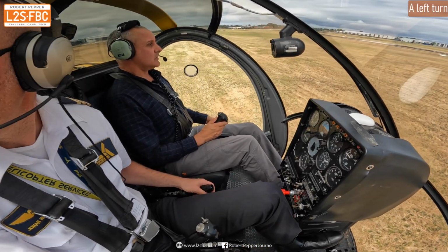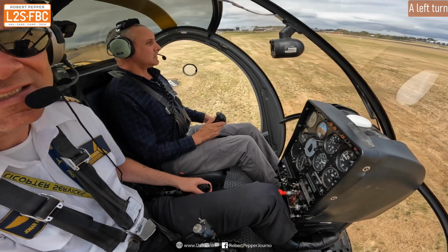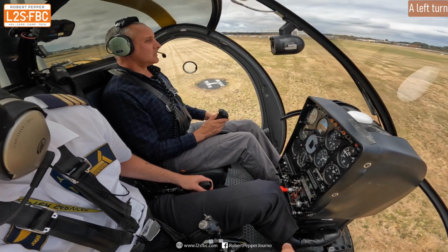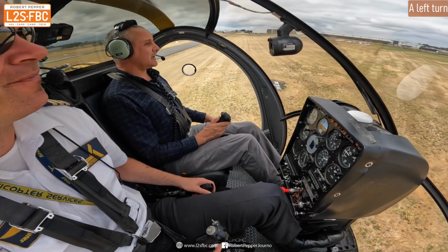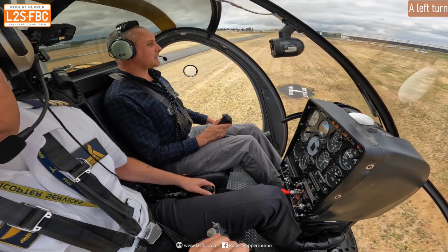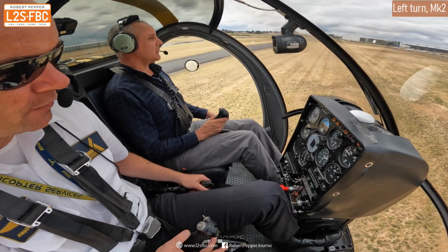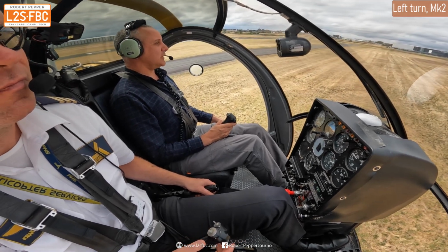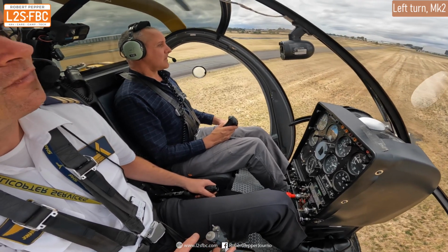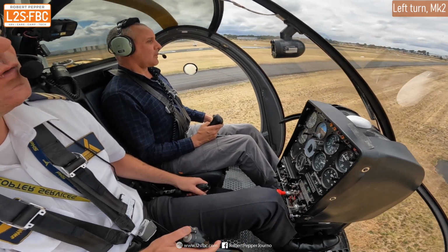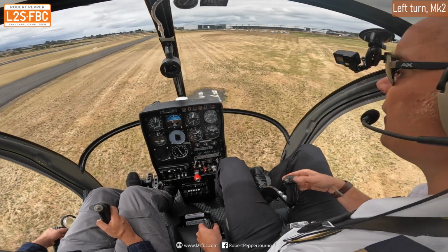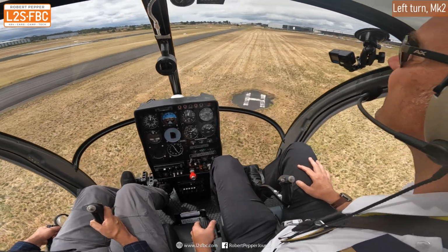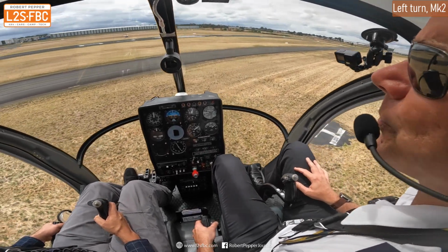Okay, that left turn was not super good, so we haven't had a crack at it. I'm not exactly perfectly hovering, but look, I'm within the same square kilometres, so that's something. So looking out to the left and just trying to get that nose round, but not too much. I'm more going sideways here as opposed to turning, so a bit more rudder. But then as the wind starts to come round, I need to slow the rudder down. So it's just that constant coordination.